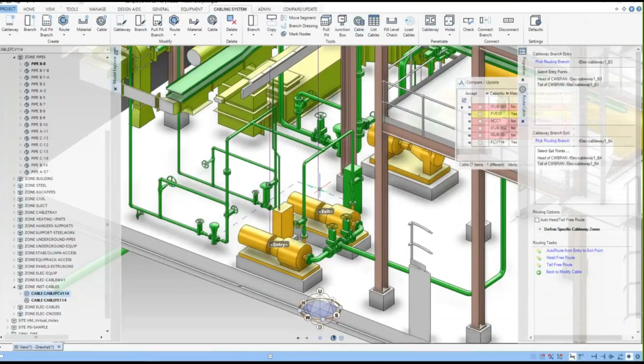And with this, if you do a change, it impacts schedule. Some of these process facilities go together like a jigsaw puzzle. They've got a coordinated way that they go together, so they've got to be in a particular sequence. If you can't meet that sequence, if you've got a vessel that's been affected and you've got to have it refabricated, it affects the installation. It may be that it's got to be put in before a pipe rack. That pipe rack can't go in, so it affects the pipes going in the pipe rack, and it has a whole compound effect, and the costs associated with that can be quite considerable.